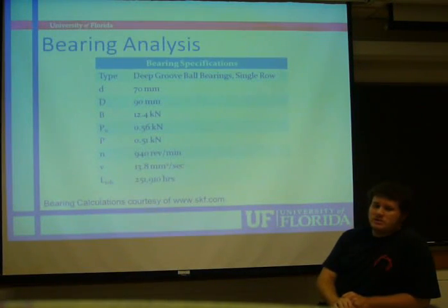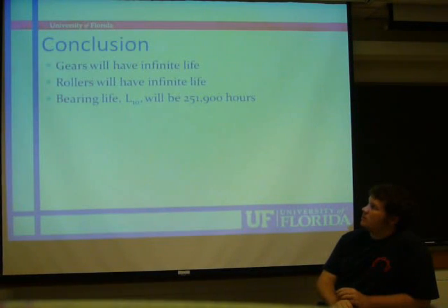The bearing analysis that we did was courtesy of SKF.com, and we selected deep groove ball bearings with a single row, and found that their life is going to be 251,910 hours. So, in conclusion, we have gears that will have infinite life, rollers that will have infinite life, and a bearing life of 252,000 hours. That's it, and thank you.